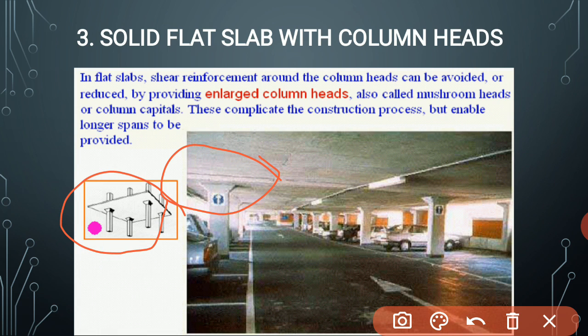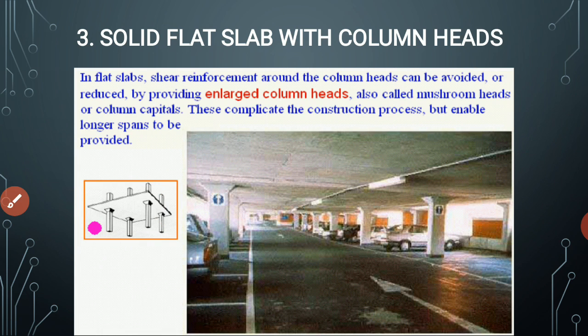In flat slab, shear reinforcement around the column heads can be avoided or reduced by providing enlarged column heads, or column capitals.